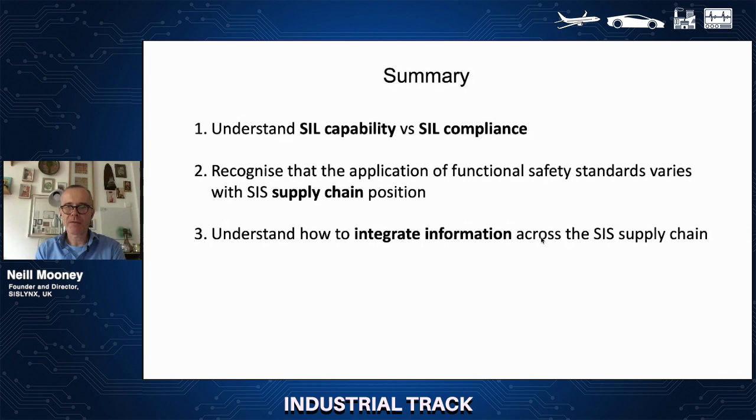So you have to, first of all, control your workflow at the supply chain position that you're at, and also the management, the functional safety management aspects that apply to that supply chain position. But this information must then be shared further down the supply chain and should be made available to the end user so that they can properly assess the low demand application for the SIL level that they are installing at the specific site location.